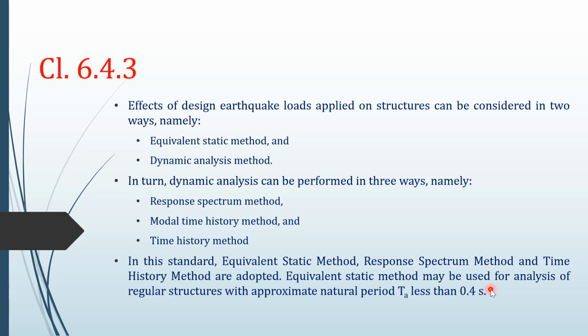Generally for such buildings and for low-rise buildings, the equivalent static method is suitable and appropriate. That means a linear static method is applicable to such regular and low-rise buildings for which the approximate natural time period is less than 0.4 second.